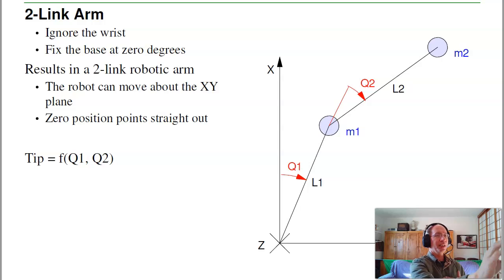In addition, I've got the wrist. The wrist can move around and figure out what I have to do to basically be perpendicular to it, to pick up the object. We'll ignore the wrist. I just want to get the 2 degrees of freedom, the shoulder and the elbow, to reach any point in 3 space, or 2 space. So, the dynamics that we'll be defining are as follows.